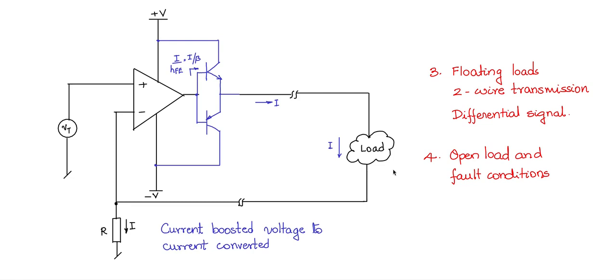Should it take that the Vt value is 0, that is the transducer output is 0, or should it take that there is a fault condition that has happened due to some component which has gone bad? The remote side load does not know that. It's not a unique condition.